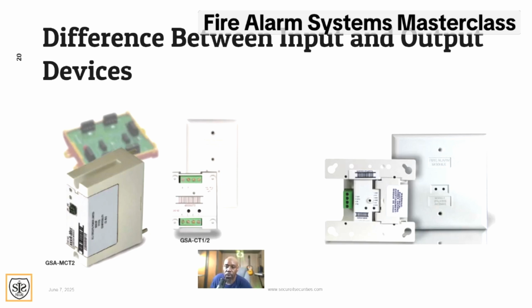That's what the output relays do. And the output relays is what connects to all of those other output functions from the HVAC guy or from the plumbing guy or from the elevator guy. We connect this fire alarm relay to their equipment so we can interrupt their equipment and shut it down when the fire alarm system goes off.